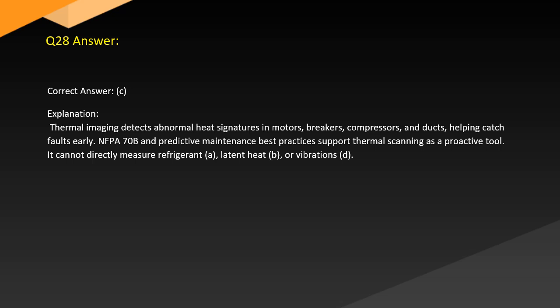Answer. Correct answer: C. Explanation. Thermal imaging detects abnormal heat signatures in motors, breakers, compressors, and ducts, helping catch faults early. NFPA 70B and predictive maintenance best practices support thermal scanning as a proactive tool. It cannot directly measure refrigerant A, latent heat B, or vibrations D.